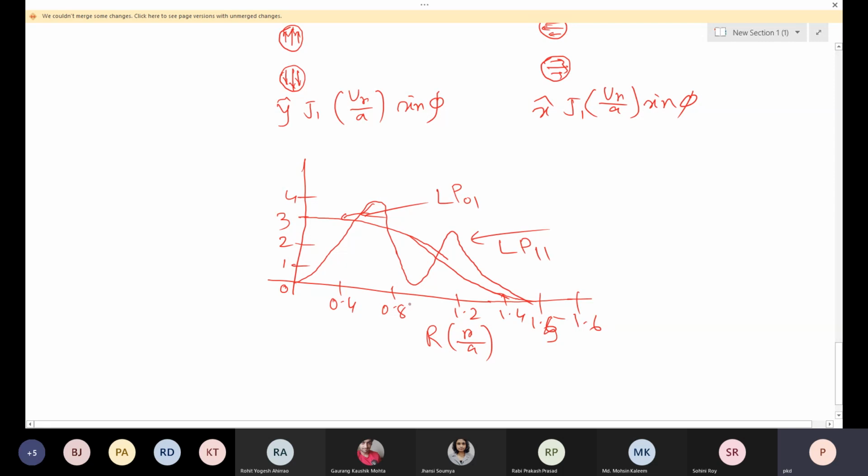The significance with respect to instrumentation is that if we want the light distribution to be very uniform for a small spot, then we have to use a single mode fiber, where only one mode will be sustained and other modes should be attenuated by twisting the fiber initially, or maybe by pressing the fiber through some micro bend, so the higher order modes will be leaked out.